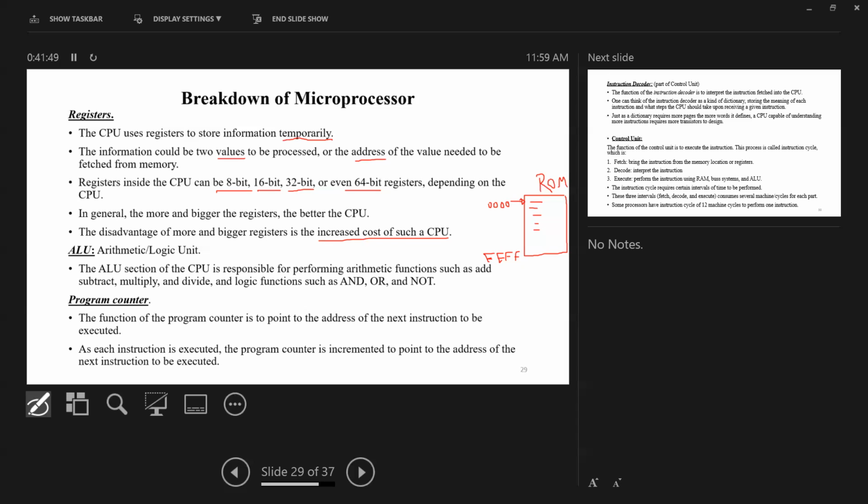So if the processor, for instance, is executing at line number 3 here, you will find the program counter is pointing to number 4. Why? In order to execute line number 4 after finishing 3, and so on. So all the time, the program counter will point to the command that will be executed after the current instruction. Is it clear, guys?